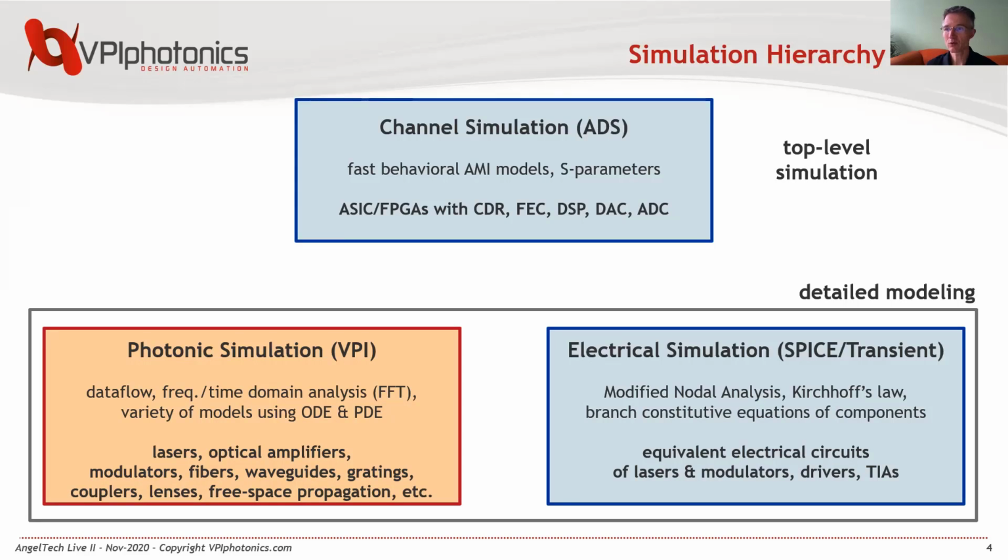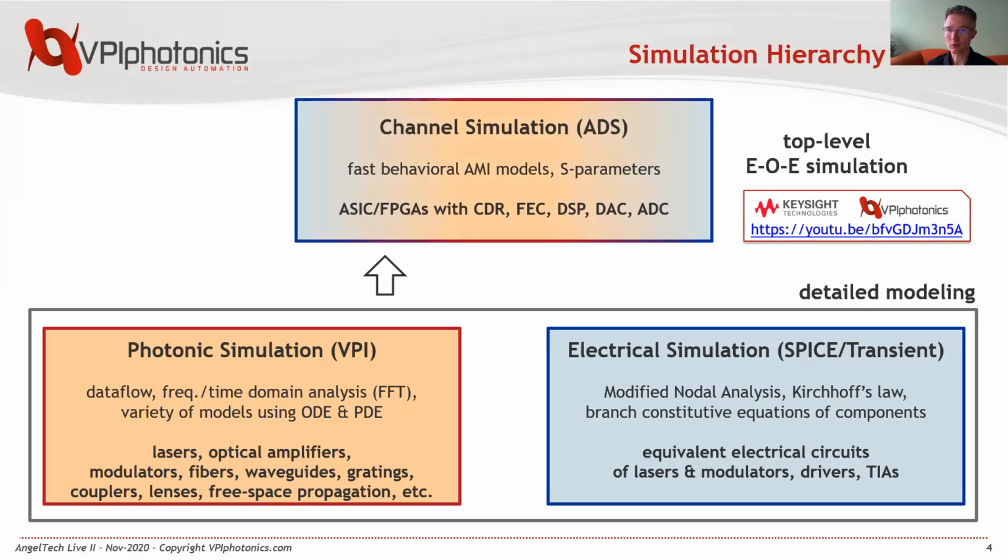On the top level simulation, you could use, for instance, the channel simulation domain by IDS, which allows you to use fast behavioral AMI models and S parameters to describe functions such as the DSP, DAC, ADCs, and ASICs. What we've showed more recently is a tight integration of Keysight's channel simulation and our photonic simulator, allowing you a top-level EOE simulation. If you're interested, dive into the YouTube video, which is depicted here. Further, what I will show you today is the integration of a SPICE simulator into our domain, allowing you the integration of all three simulation domains.